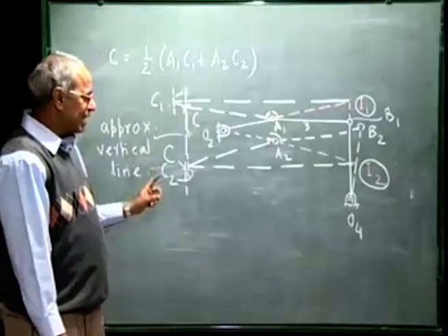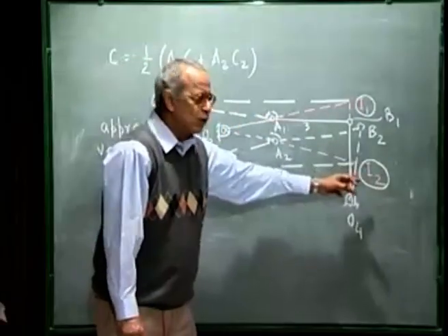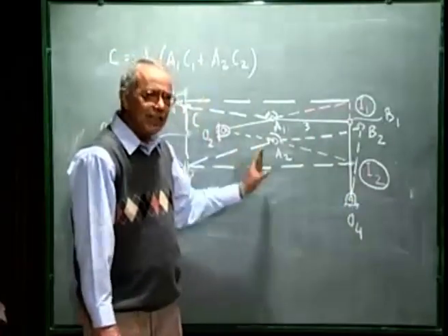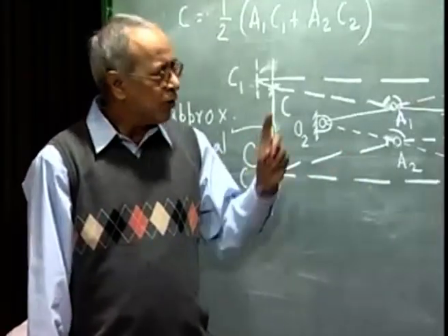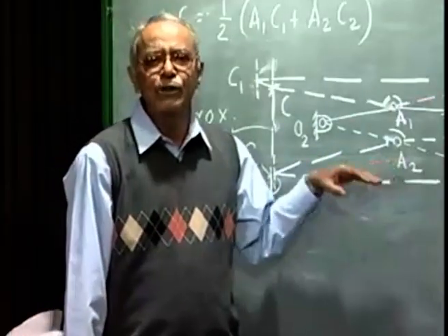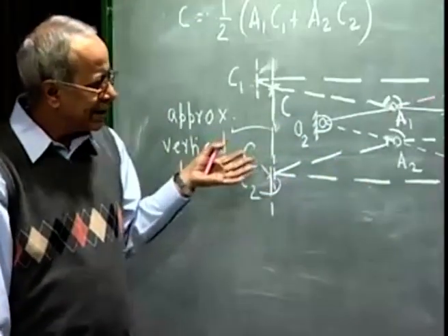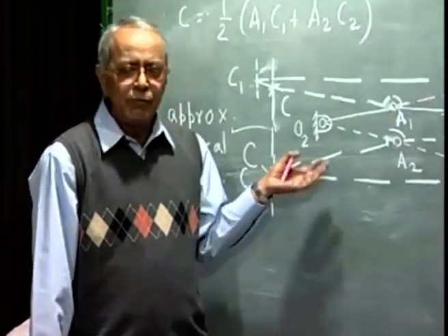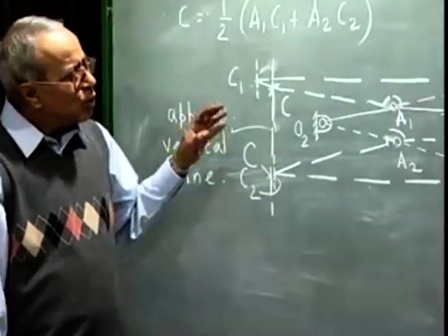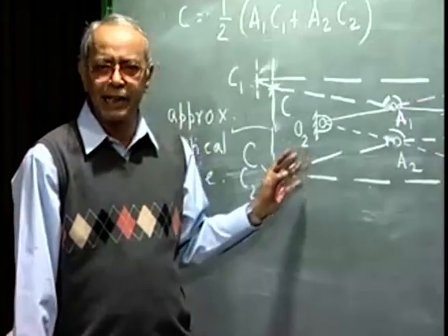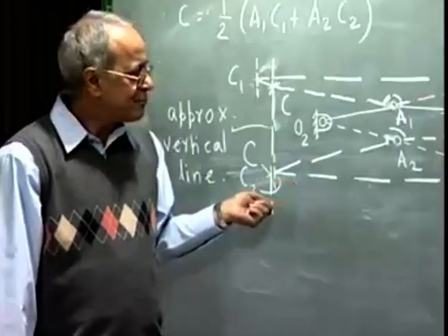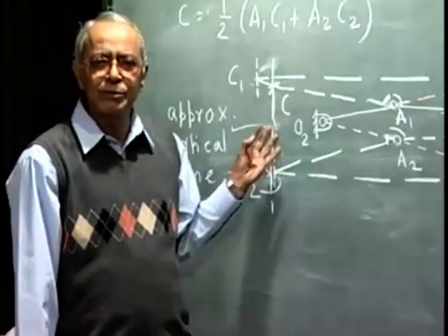It must be emphasized that with a 4R link with any point on the coupler or any choice of link length, I can never generate a perfect straight line. For that we will discuss later that we have to go for linkages with more number of links, that is more than 4. Before that, let me discuss two other approximate straight line mechanisms which are historically famous, which are designed by mathematicians to generate an approximate straight line.